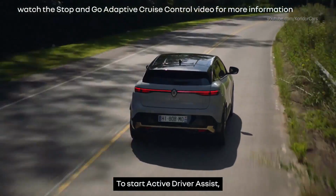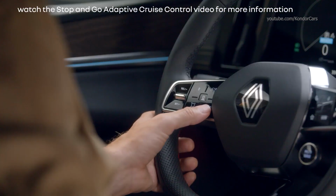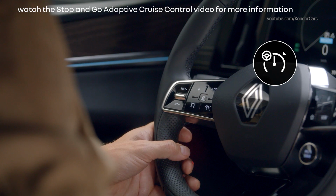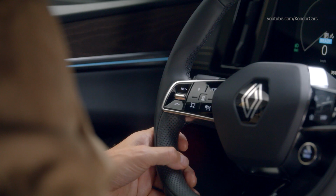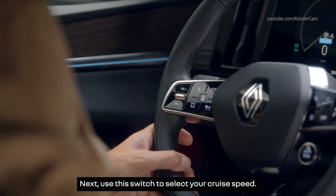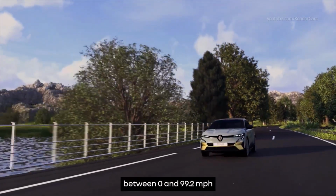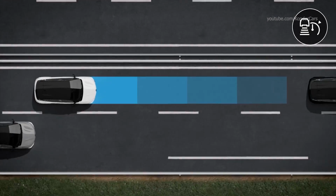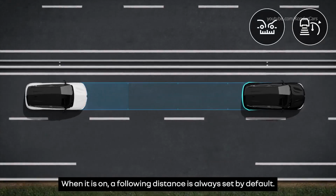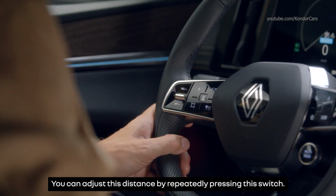To start Active Driver Assist, first press this switch to turn on the stop-and-go adaptive cruise control. This indicator light appears on the instrument panel along with the message Adaptive Cruise Control On. Next, use this switch to select your cruise speed. You can use the stop-and-go adaptive cruise control between 0 and 92.2 miles per hour or 0 and 160 kilometers per hour. When it is on, a following distance is always set by default. You can adjust this distance by repeatedly pressing this switch.